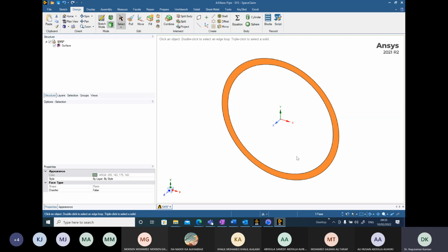So now I want to create another sketch which shows the trajectory by lines. So first I have to enable the XZ plane for a sketch. So I move my cursor on X-axis, press the control button, left click and select the X-axis.